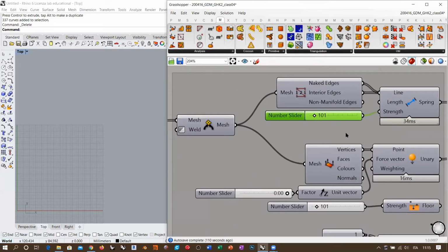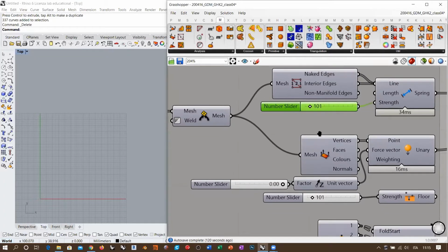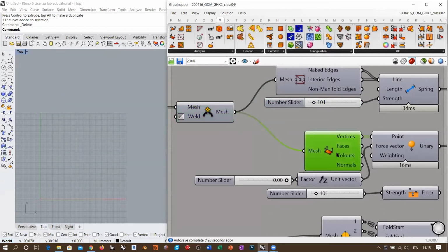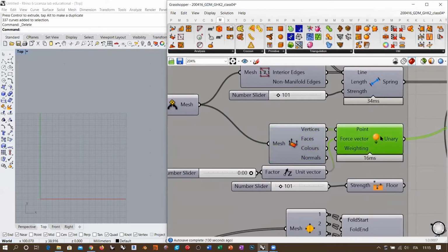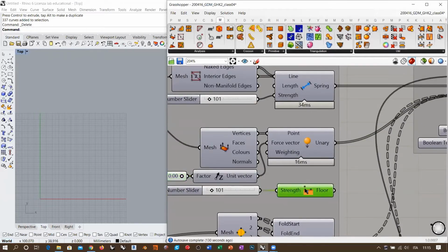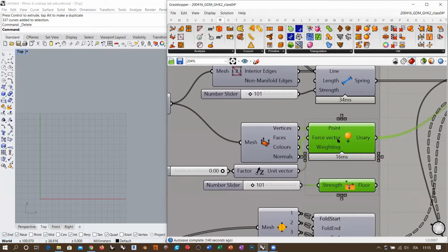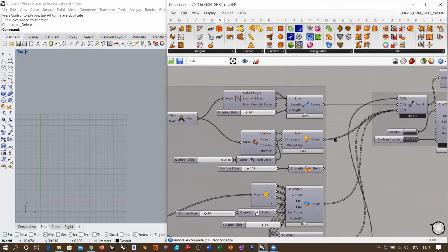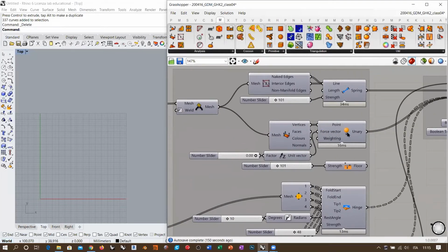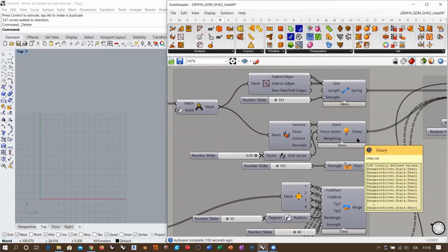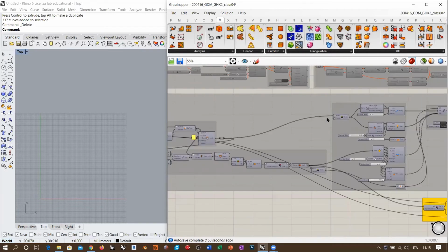And then I also applied some gravity in order to start playing with different scenarios. Okay, so I took the quad mesh, extracted all the vertices, and I am applying a load to this. The load is initially set to 0 because you see that the floor is disconnected, so I don't want this mesh to fall. So either I leave the load at 0, or I plug the floor into the solver. But in any case, I will work with load 0 for now, and then we will switch things with these 2 components here. That's it for the mesh, okay?